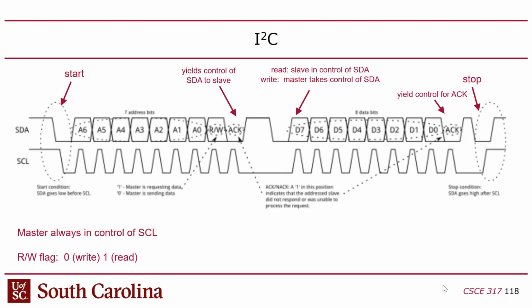and drive the data down as an acknowledgement, right? So it drives it down, then it waits for the master to raise up the clock. It holds that down until the clock then goes back down, right? So the target of this transaction has to pull that down to acknowledge. If it doesn't acknowledge and the master sends the clock up and brings it down, then that's a NACK. That's a not acknowledge, in which case I'm done. I give up. No one's listening. Right? That's the idea.